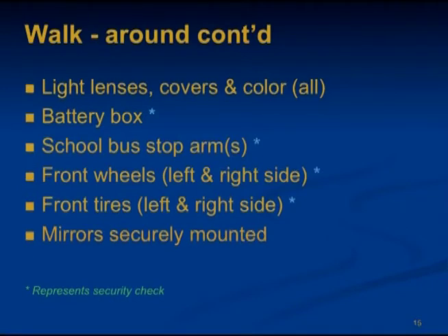Check the glass on all windows should be free of illegal stickers, clean and not cracked. Windshield wipers should have good contact with the glass. Mirrors should be mounted securely with no broken or cracked glass. They should be clean, properly aimed, and tightly adjusted.